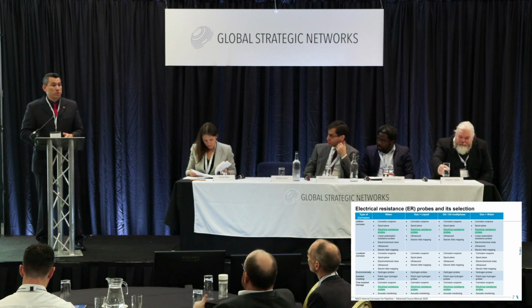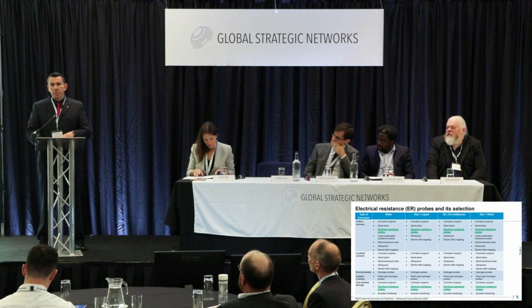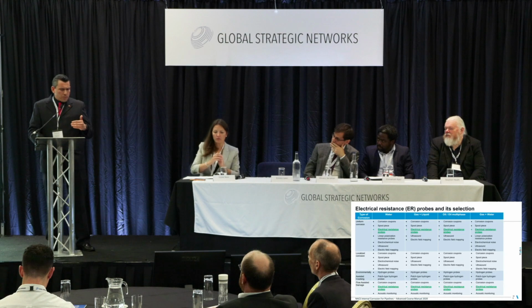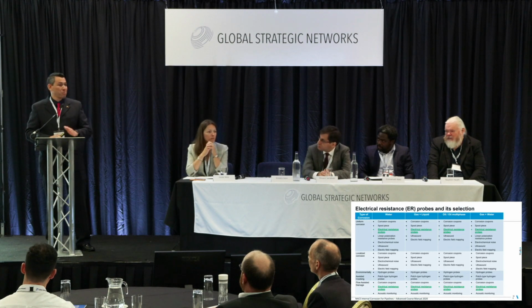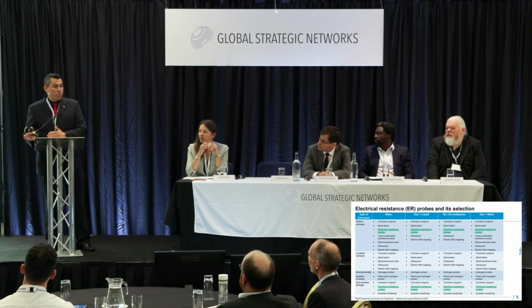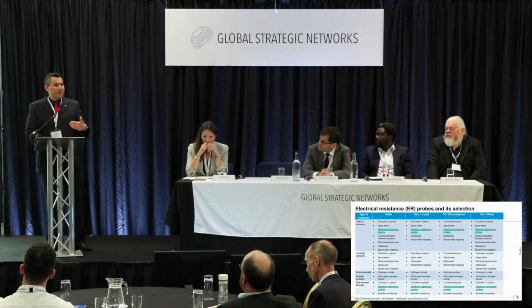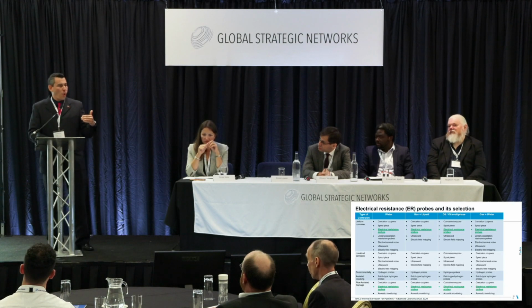That's very important. If you have no clue what to expect, try to get support from professional, experienced people in corrosion to identify your expected degradation mechanisms. Because it would be a pity if you invest a lot of money, for example, installing corrosion coupons or corrosion probes to try to assess hydrogen embrittlement. It's not going to work. You need hydrogen probes to assess hydrogen embrittlement. Therefore, it is important that from the early beginning, you have a clear picture of what your system is.